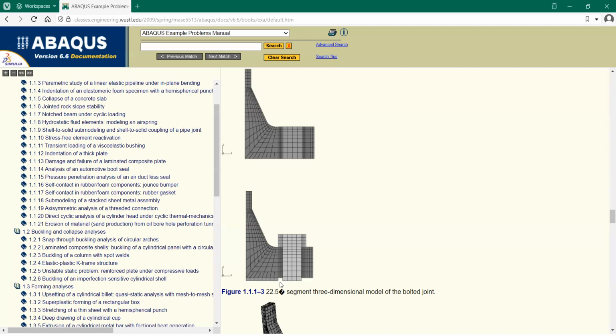What is the necessity of having a fine mesh here? This is a different material and this is a different material. And when they come into contact, will they create some stresses? What is the reason? Why is this finely meshed? And this side is also finely meshed. And above this, again, this part is finely meshed.